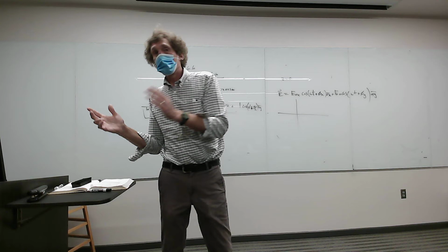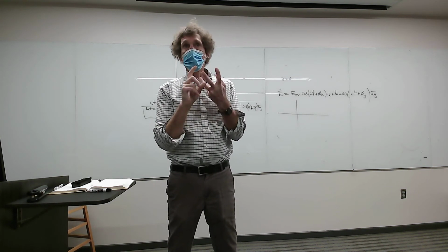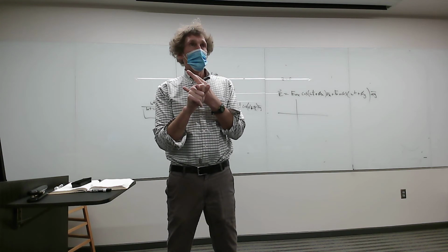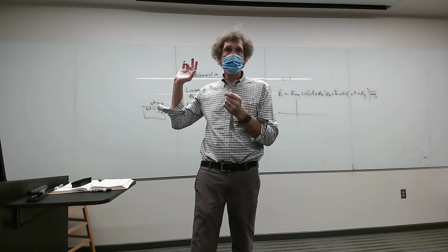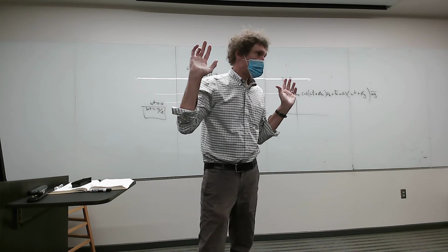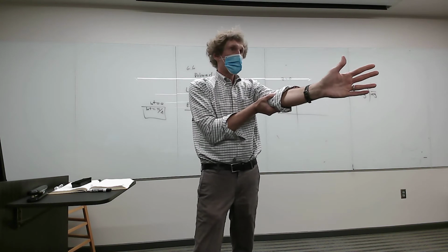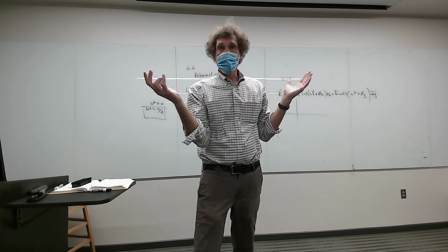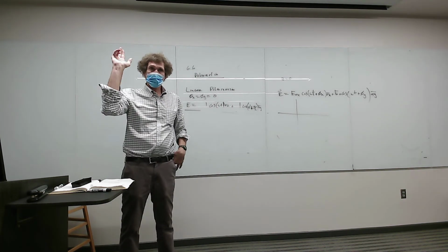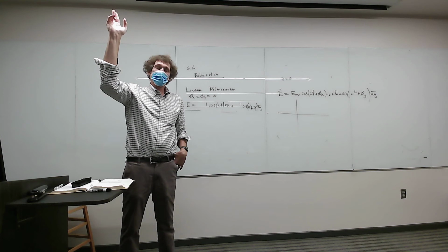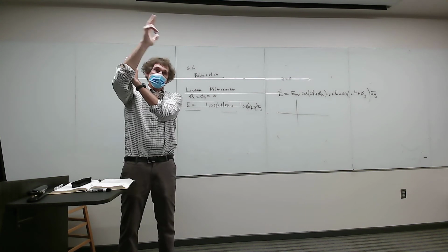In our book, you have theta and phi, right? It's the two angles for circular. In the real world, with radar work, aircraft work, my wife's doing work at Archangel. It's an embedded systems thing. She's a trained electrical and computer engineer, a master's. All the stuff that they're going to do is azimuth and elevation. All right? It's not theta and phi. That's for us guys in electromagnetics, where we do theoretical antenna design. And you know what I'm talking about when I talk about that. Azimuth is theta, we just call it theta, is always from a vertical axis, how big the conic angle is, the opening, right?